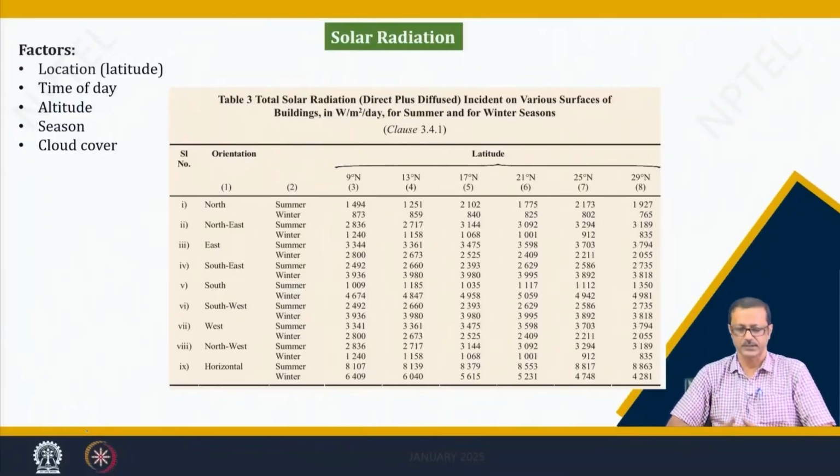Some of the radiation may penetrate through the windows, the glazing or the skylight, and finally it will accumulate inside the room, and the temperature of the room will increase, so the total thermal gain, the heat gain, will also increase. This solar radiation is different on different surfaces.